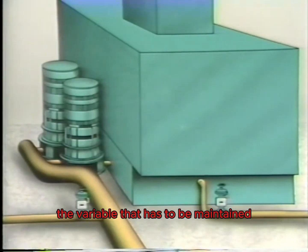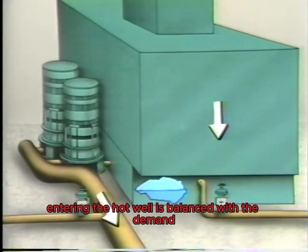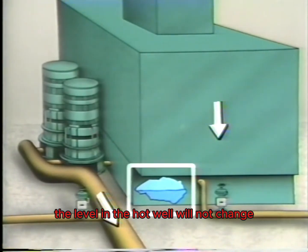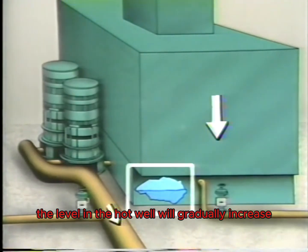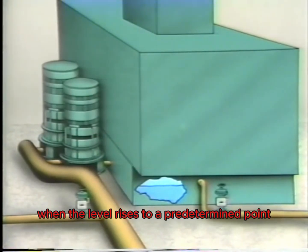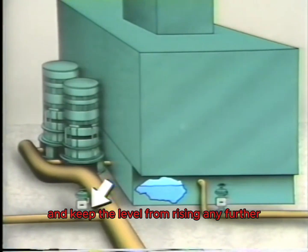Now, in this system, the variable that has to be maintained is water level in the hot well. If the amount of water entering the hot well is balanced with the demand for water from the hot well, the level in the hot well will not change. But if the amount of the water entering the hot well is greater than the demand, the level in the hot well will gradually increase. When the level rises to a predetermined point, a valve starts to open in this pipe called the draw-off line to drain off the excess water and keep the level from rising any further.